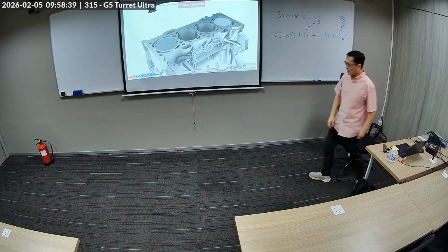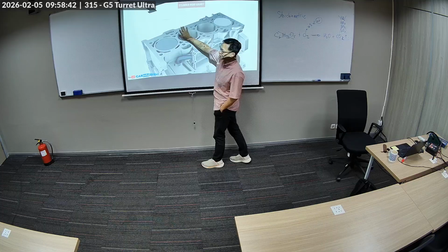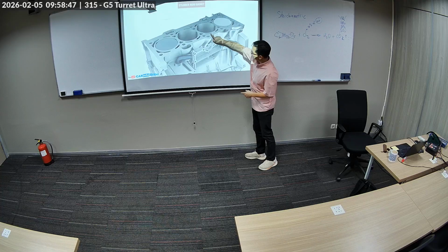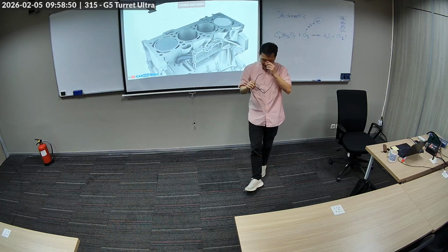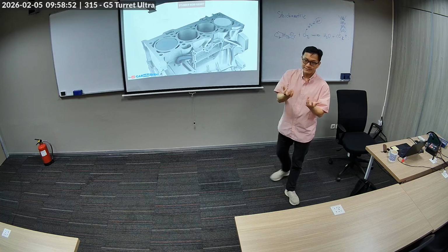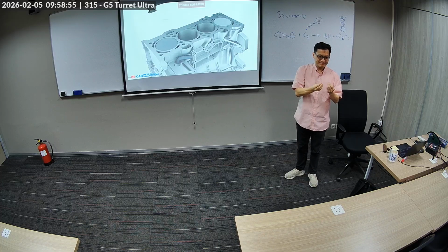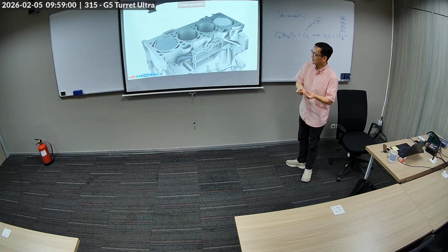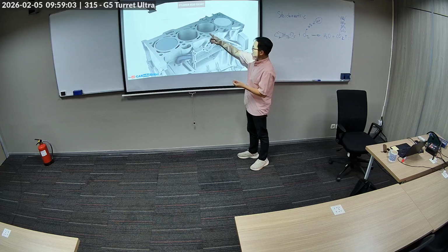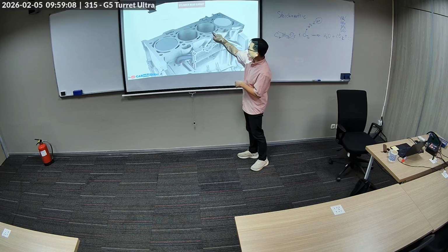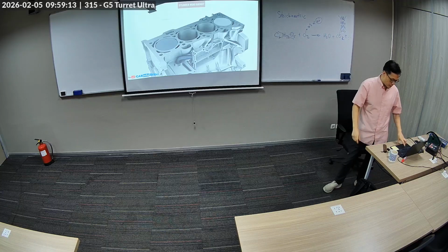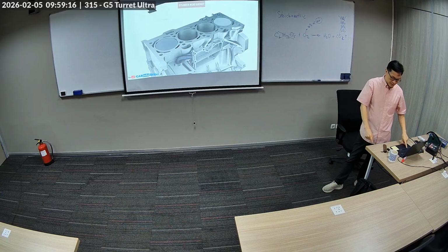That's the head gasket. That's one of the failure points also, the head gasket. If you blow a head gasket, one of the ways you tell is that your oil is mixed with water, like a soap-like paste, like a toothpaste. That's one indicator of a blown head gasket. Because this is the water channel, and you got oil here, obviously. So you get it mixed up between the oil channels and the water channels.